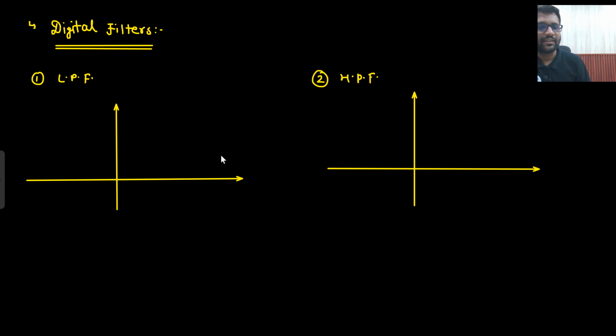Now digital filter, practical digital filter. What are we going to make? What kind of practical digital filter will you see? It will provide the maximum gain at omega equals 0, and then it will keep on decaying, and at pi it will become 0. Is that clear to you? Did you understand this point? Right? And a similar thing is happening here as well. At minus pi it will become 0. Say yes or no.